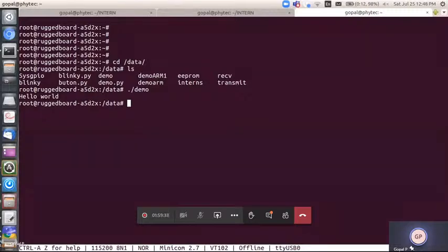These two are the best options. At the basic level you can use an SD card, and at the advanced level, once you are hands-on, you configure Ethernet or TFTP between your embedded board and your host PC, and you can transfer files quickly without any disturbance. That's one point to note here.